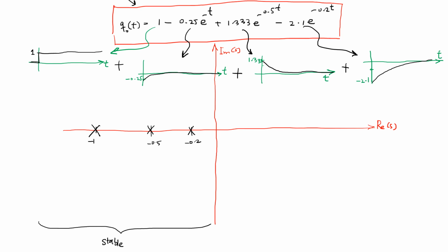We have gone through all the details in a very careful fashion. We have seen how the transfer function is structured, and we have used the block diagram method to have all the individual blocks cascaded, and from there we wrote one transfer function, and then we solved it using the partial fraction method, and eventually reached the time domain expression. And then we have used the concepts of S-plane that we have explored along the way to see how the poles are going to be placed. In a nutshell, we can observe that you have 3 poles. All the poles are placed on the left half of the S-plane, and all the poles are real as well. So that's why the response is going to be much simpler.